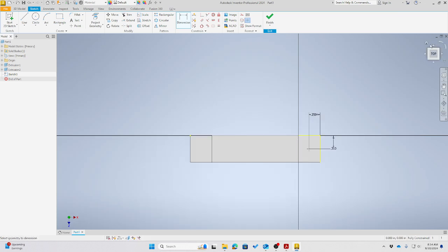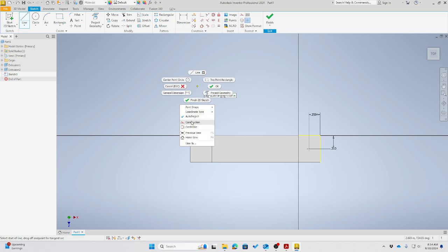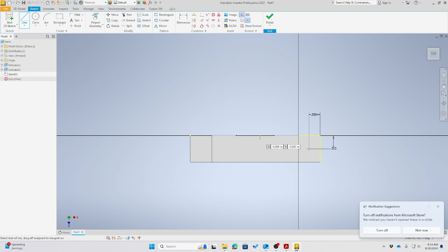So now I'm going to use the sketch mirror function to mirror this one to the other part. In order to do that, I need to define the line from the middle of this sketch. So I'm going to use the construction line. Click the line, move your mouse to the graphic window, right click, click on construction, and move the mouse, and you're going to be able to find the middle. This is the green point, it's the middle of that line. Click it and go up to here.